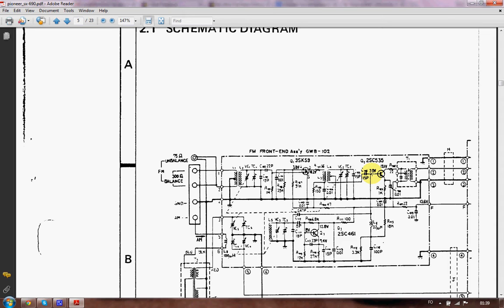Where is the component which made it so the 20 volts cannot reach this stage? And no, it's not going to be in front of here, because we're looking for voltage, and voltage can still be there if there's a break somewhere, but voltage can't reach this side if it's broken before. But if it's broken afterwards, it doesn't matter.